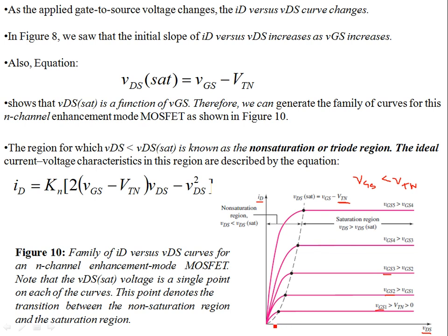The transistor being in cutoff means that your ID is very small. Then there could be a leakage current, but that's not significant. So this is if the transistor is off. Now if you have satisfied the condition that the gate voltage is greater than the threshold voltage, there are two ways to find the current that flows through the transistor from drain to source, and to see how you can evaluate that analytically.